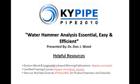Okay, from Sean Wang, what is the difference between the MOC and WCM in terms of friction effect? Well, all the studies we've done show that there's no distinguishable difference between looking at the effect of friction on a wave that travels from one junction to another, maybe 500 feet or 1,000 feet, as opposed to the method of characteristics, which may make that calculation in 5 or 10 steps.